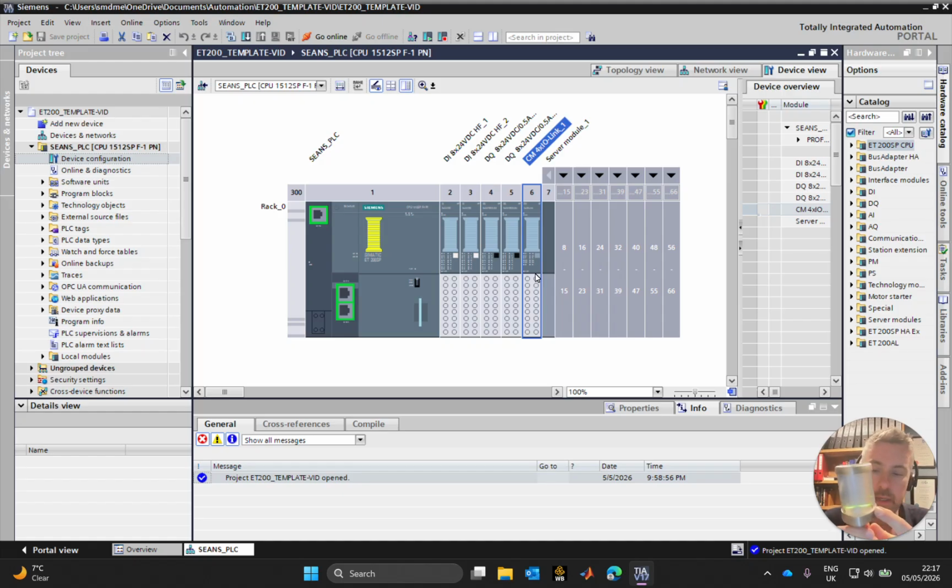Now I could see in the light here that there is like a lime green pilot light emitted, and it's on solid. What that indicates is that the unit is powered. A flashing light, or intermittent light, indicates that not only is it powered, but it's communicating. So there's no communications with this. This is just receiving power from the IO-Link master, but there's no data transfer happening. This is what I need to instigate. I need to get this going. I need to get the two talking, the PLC and the light talking.